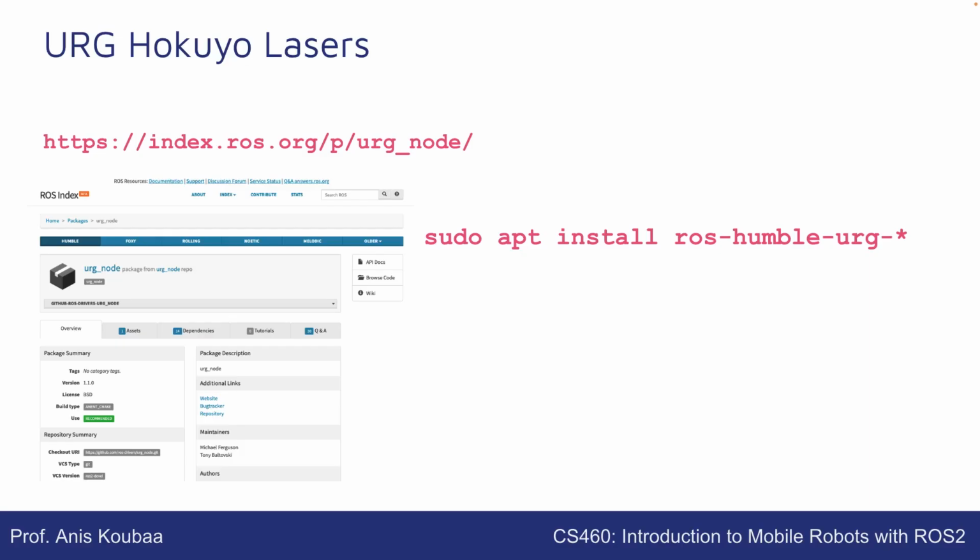Okay, so now basically when you work with ROS2, you can work with almost any laser scanner in an agnostic manner. The most important thing is that you need to have a driver, like for any other device. If you have a camera, motors, a laser, any sensor or actuator, and you have a ROS driver, then later on, from a coding perspective, the code is completely agnostic to what kind of hardware you are using.